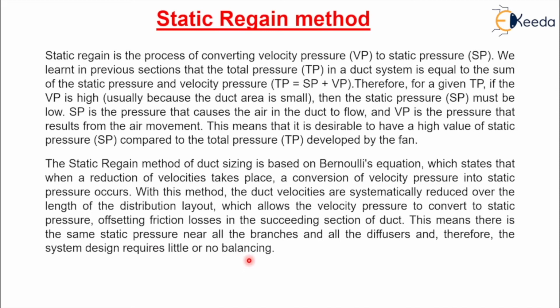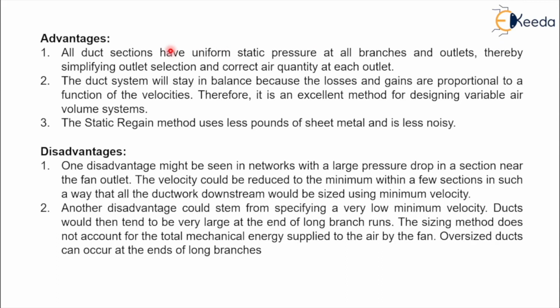In this case, if the velocity is reducing and only static pressure is there, then there is very little requirement of balancing in the system. Okay, this one is the static regain method. What are the advantages and disadvantages of the static regain method?